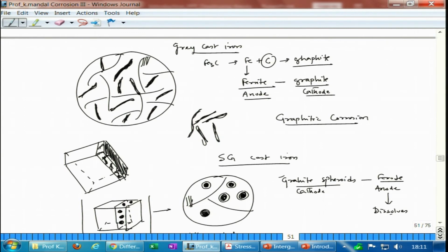So, there what happens, both dissolve first and then the pure noble metal deposits back. In case of copper zinc, copper deposits back. In case of silver zinc, silver deposits back. So, there we see that preferentially both dissolve and then one noble metal ion deposits back, but in this case we do not have dissolution of both, rather one dissolves and the second one is left behind.